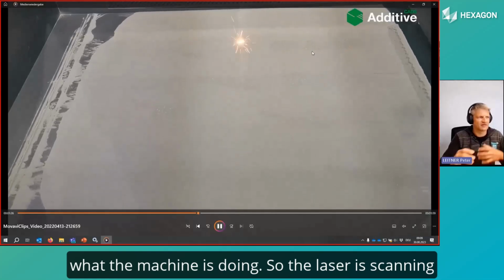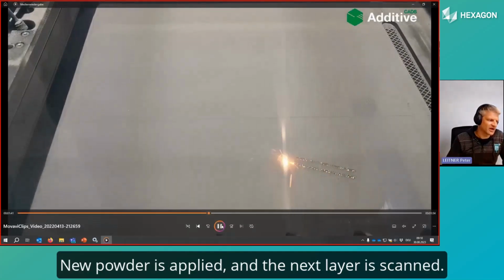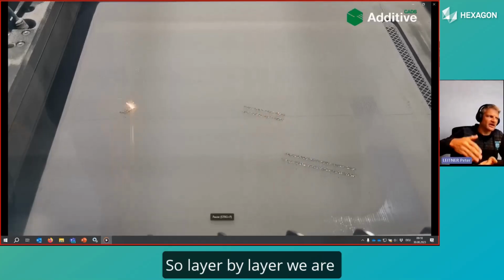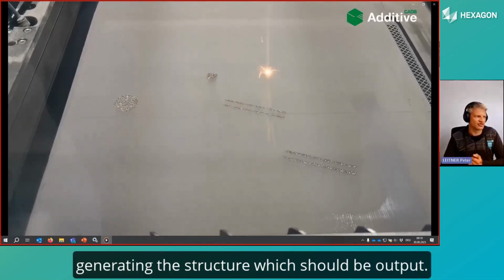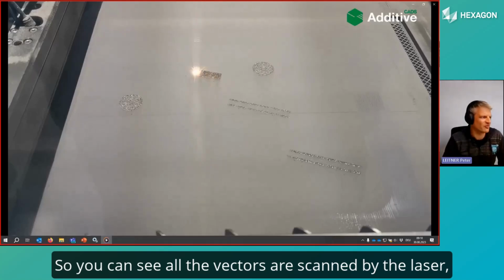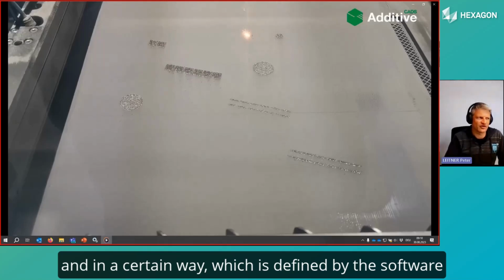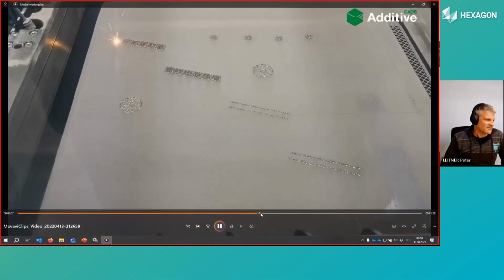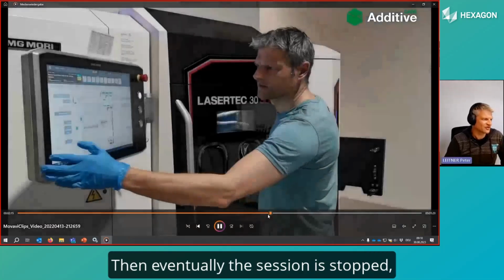So the laser is scanning the areas which have to be scanned. New powder is applied, and the next layer is scanned. So layer by layer, we are generating the structure which should be the output. So you can see all the vectors are scanned by the laser, and in a certain way which is defined by the software AM Studio, which I will show you later on in detail. Then the next layer is applied, and then this session is stopped.